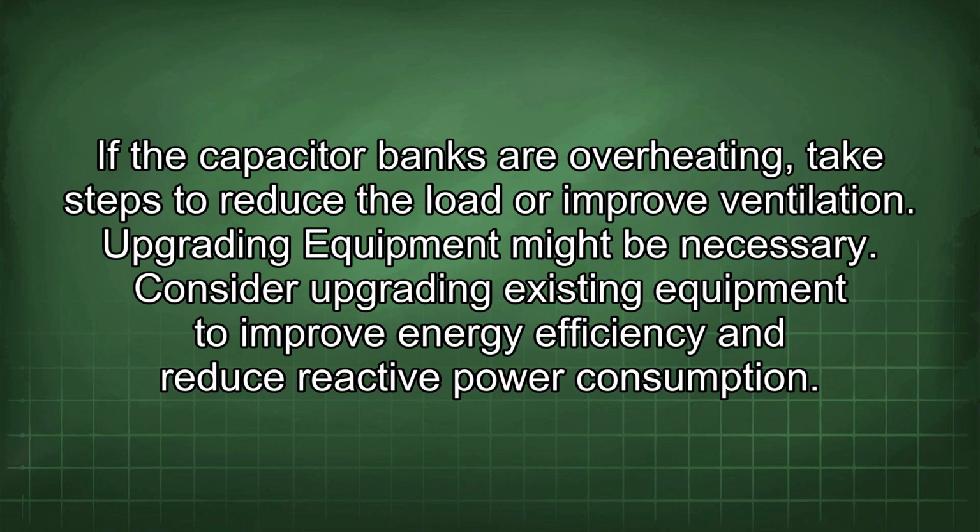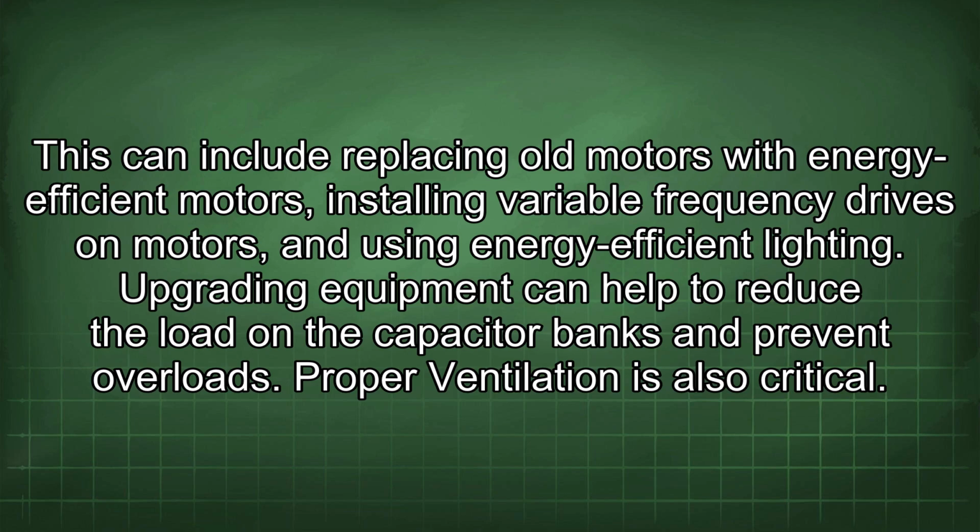Upgrading equipment might be necessary. Consider upgrading existing equipment to improve energy efficiency and reduce reactive power consumption. This can include replacing old motors with energy-efficient motors, installing variable frequency drives on motors, and using energy-efficient lighting. Upgrading equipment can help to reduce the load on the capacitor banks and prevent overloads.